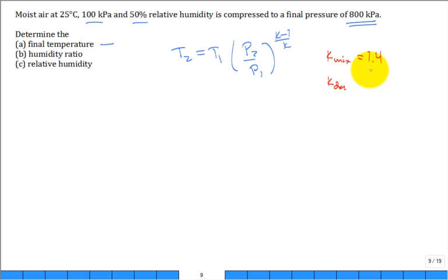So we put in the absolute value of temperature, and we can calculate that the temperature at 2 coming out is 200 and around 70 degrees C, and that's for a perfect compressor where isentropic efficiency is 100%. I know I rounded off to 2 significant digits. If it wasn't a perfect compressor, do you think Home Depot is going to sell you a perfect compressor?